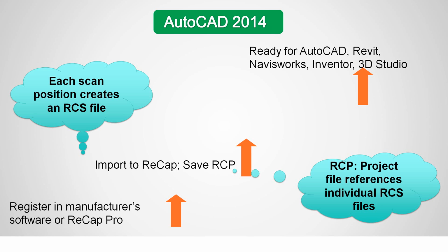Now, one of the issues with AutoCAD 2014 was that the viewing quality of point clouds really reduced dramatically as you overloaded the AutoCAD environment with scanned data. So many users would crop out sections of data, sections of interest, and work in smaller chunks of data, and reducing the overall amount of data inside the environment would result in better viewing quality.